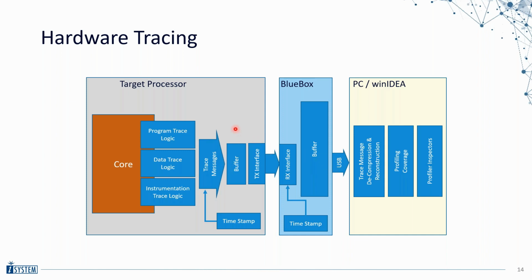The problem with the on-chip trace buffer is that it's usually rather small, so you won't be able to record a trace for a long time. If you're only recording running task and running ISR, you might still get a couple of milliseconds, but it's definitely not in the seconds range as I claimed earlier. So that's one approach.